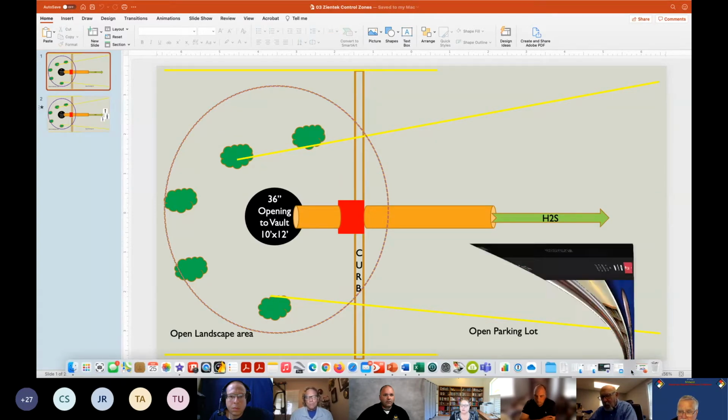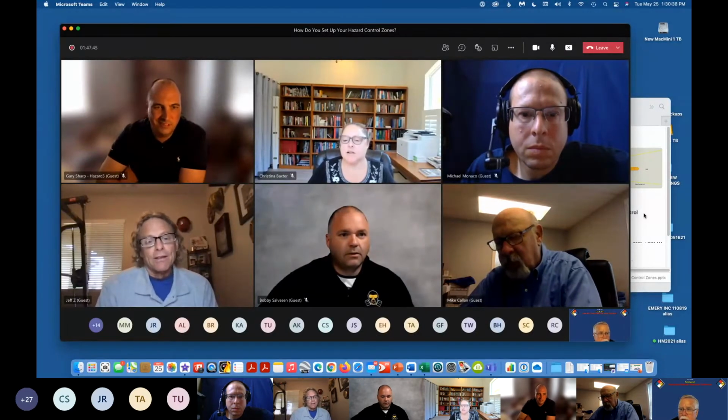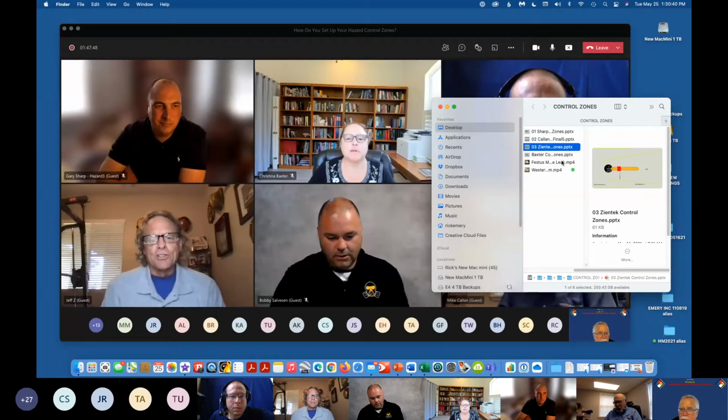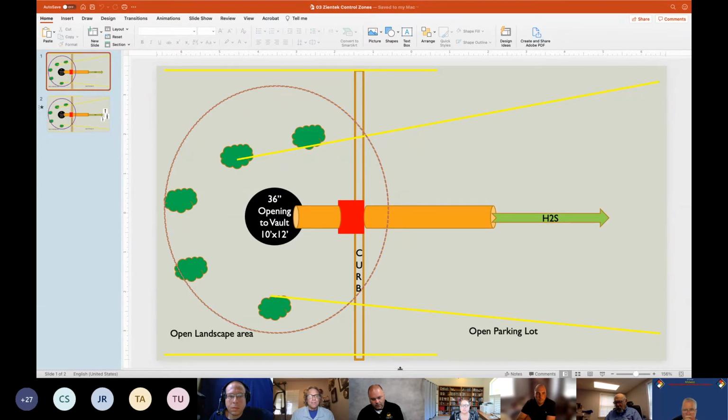Well, if it's no big deal, why would it be classified in a fire diamond as a 440, right? So it's a huge concern to us. The good thing about it is it gives us indicators because it's such a strong smelling product. However, after about 120 parts per million, we get that olfactory breakdown, and then all of a sudden we think it's gone. So what we had in this situation is we had two gentlemen in this vault below ground, but we were getting over 200 parts per million at the entrance.